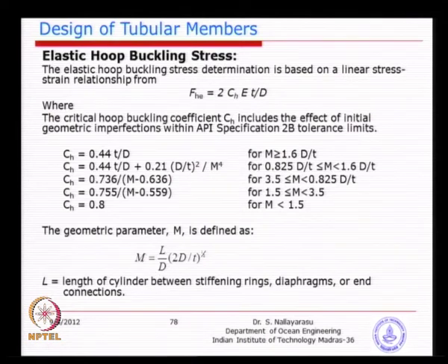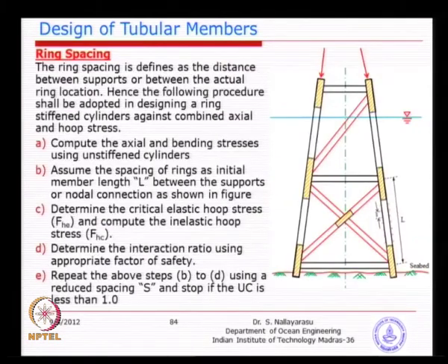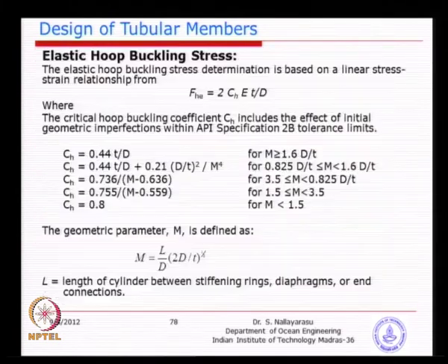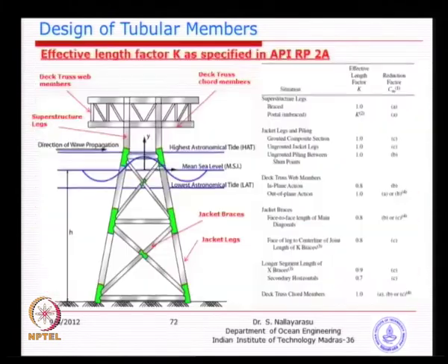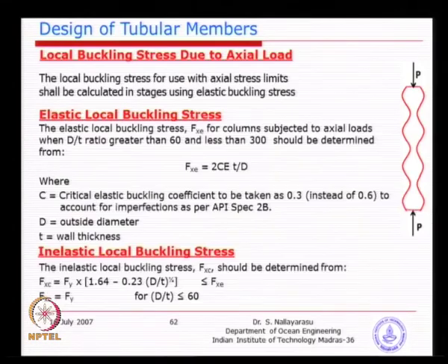Suppose you fail to do that, for example, you go to this diagram. The original length of the member is like this, but then what can actually prevent this member from local buckling? You provide rings like this. You see here in tiny dots, we have circular rings preventing the pipe from becoming that waveform.